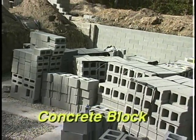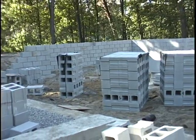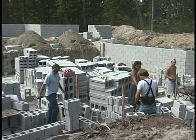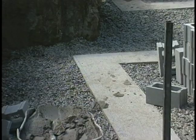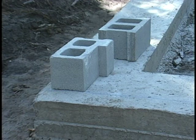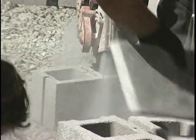Concrete blocks are used for foundation walls and other masonry construction. Concrete block walls are generally not quite as strong as poured concrete, but can reduce construction costs. First, use a chalk line to mark the location of the wall on the footer. Then, lay the first course of blocks without mortar to check the layout. This will avoid unnecessary cutting of the blocks.